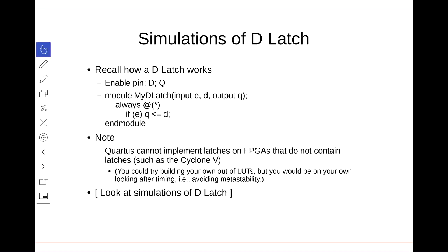Okay, so I'm going to look at simulations of this and try to get it stuck, if I remember correctly. Remember that a D-latch, the Verilog code, looks just like this. A D-type flip-flop can be made using two D-type latches in a master-slave arrangement. So if I can get this in a metastable state, I can get a D-type flip-flop into a metastable state. You can read the rest yourselves. Let me now try to run a simulation of this.